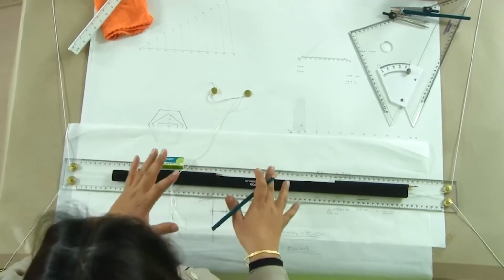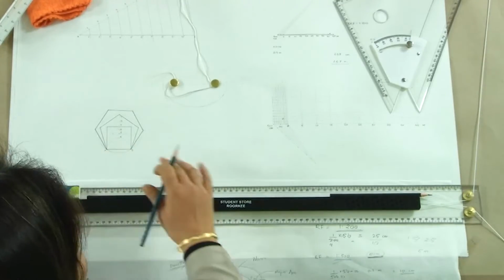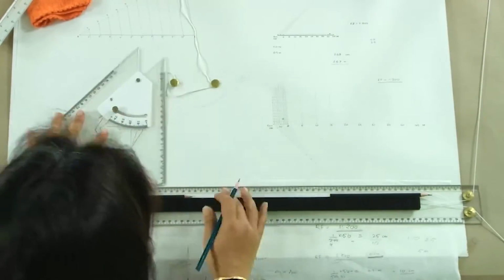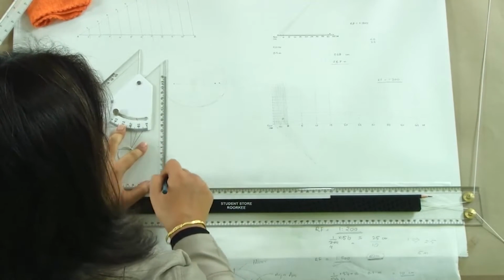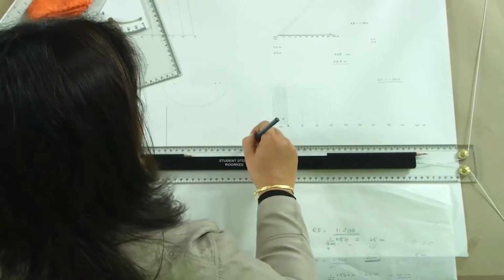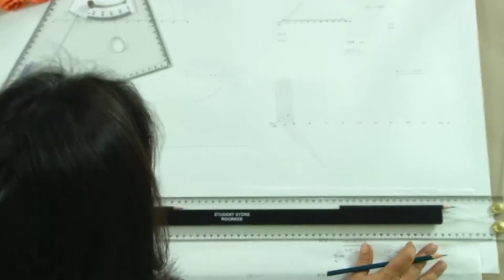However, we often do not draw using this method in engineering drawing, in engineering graphics, and what we need to do is we need to know the directrix, the distance of focus, the eccentricity, and we will draw using that method. Now, if we have to draw using directrix and that method, so what we have here is a directrix which is given. We will draw an axis of the ellipse perpendicular to it at any point. It is not fixed. These are just generators.